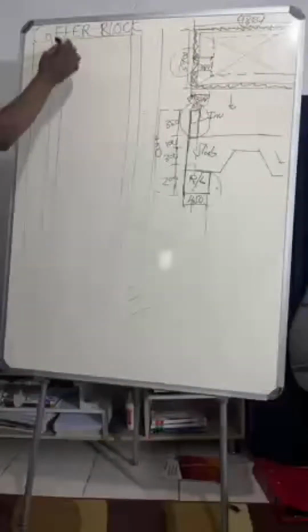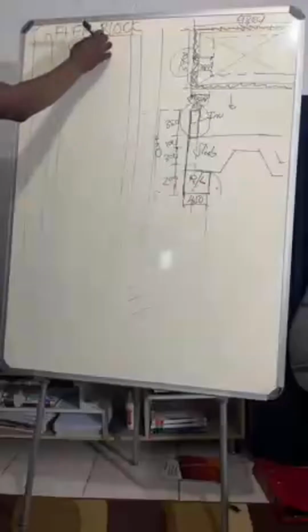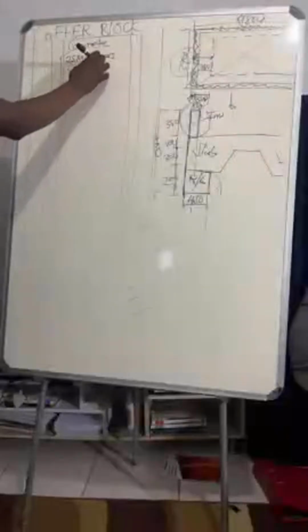We are starting with concrete. So let's say concrete. I'm not going to write a description; you are using the standard system. If we check on the specifications, on the beams and the columns they say 25 MPa. You're just going to say 25 MPa mass concrete for the inverted beam. Do you have the height of the inverted beam? Yes, you do have it.